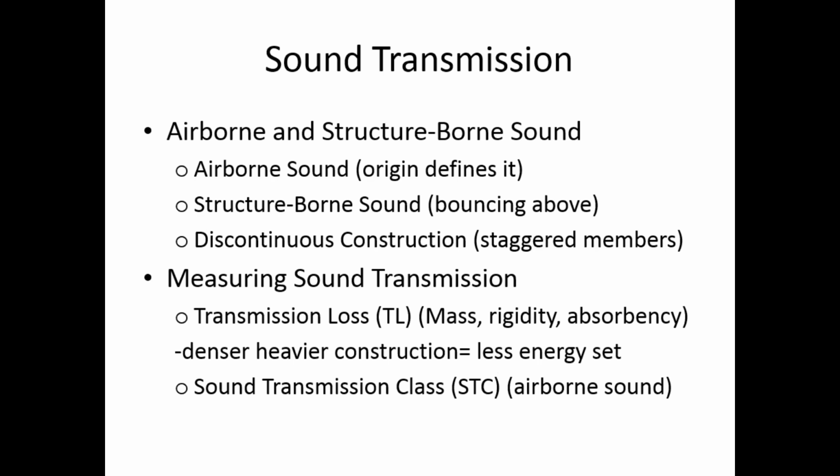Discontinuous construction. I had next to that the most important thing that the book informs us of: we want to stagger our members sometimes, our building members. So one way to stop issues with construction and leaks of sound is for us to either use flooring atop of solid surfaces, like concrete, and we have a chart to go with that.